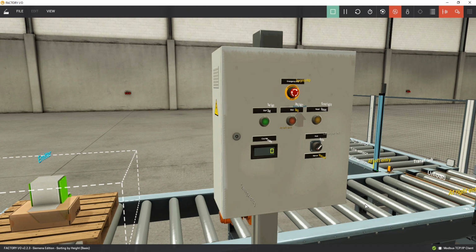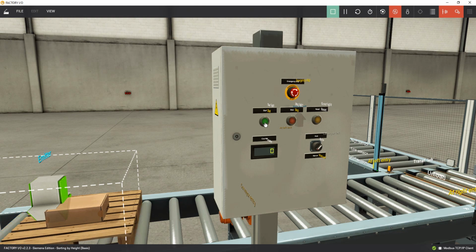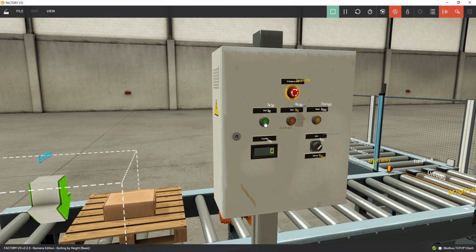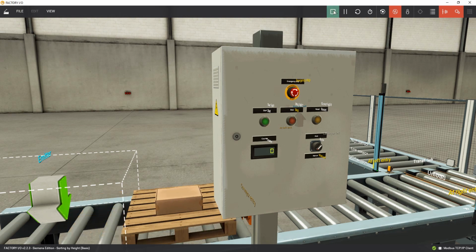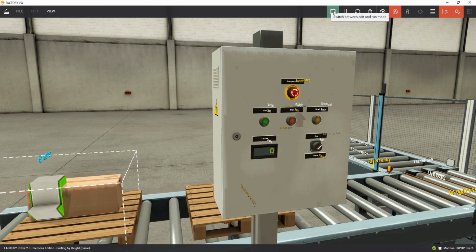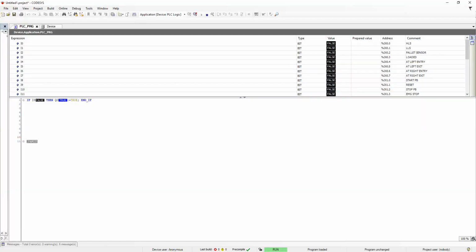When I let go, the conveyor belt will stop. I press the start button, the conveyor belt moves. I let go of the button, the conveyor belt doesn't stop moving. So meaning that we don't need to latch. Whenever you tell a signal that it starts, it eventually starts indeed. You see, it says true, and it will remain true until you break the signal. So every signal you create, you must always have a way to break it. Otherwise, it's going to create problems for you.